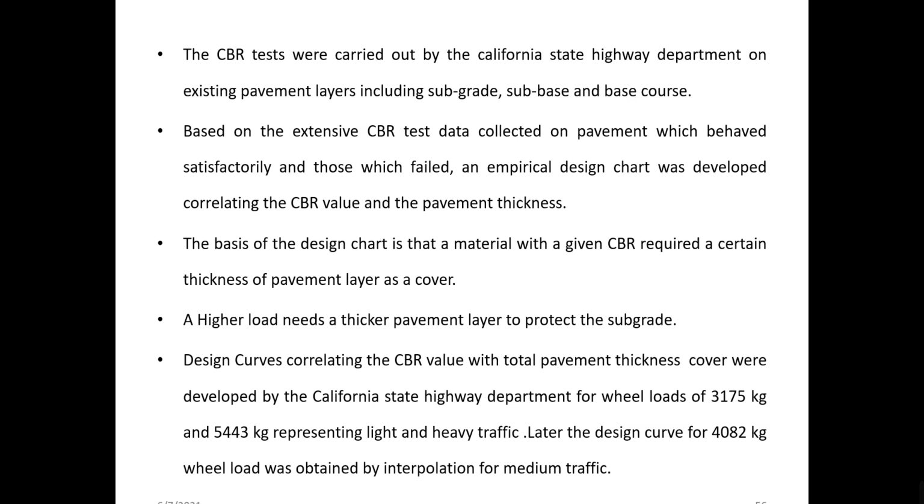Okay, subgrade is nothing but locally available material or locally available soil that is routinely available to us during the construction of the pavement. Either it might be a weaker soil or it might be a stronger soil. Okay, if weak soil is met with during the time of construction, it has to be stabilized well before the road construction is carried out. Otherwise, the cost of construction of that particular pavement is going to increase in terms of increased thickness. Okay, so hence we first of all have to stabilize the subgrade soil.